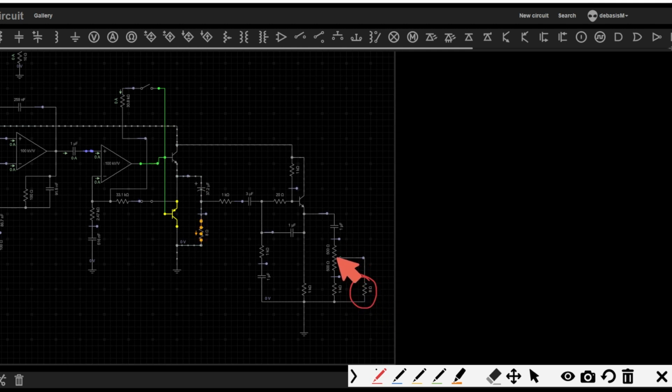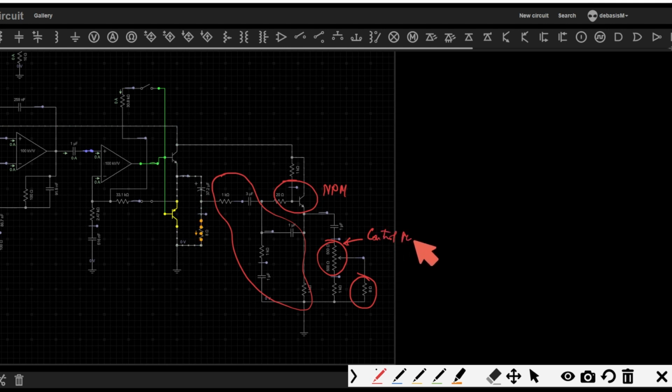You adjust this resistance by rotating the knob of the bass adjuster, and you give a higher or lower voltage across this resistor. By adjusting this knob you can adjust the voltage of this subwoofer and accordingly the impact or sound of the subwoofer. So effectively the bass boosting section is nothing but a low pass filter, which encompasses this section, and a class A amplifier using an NPN transistor, and you have this control knob.